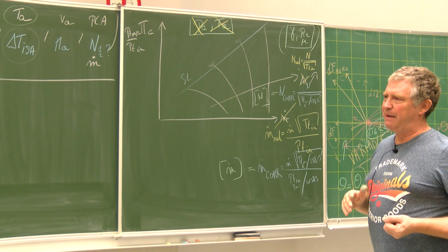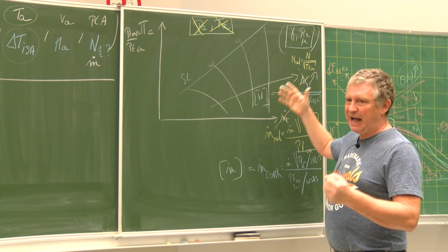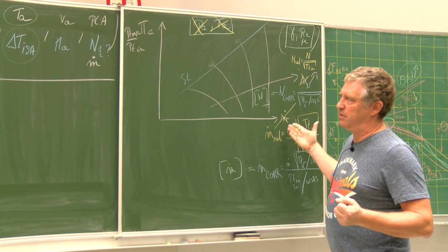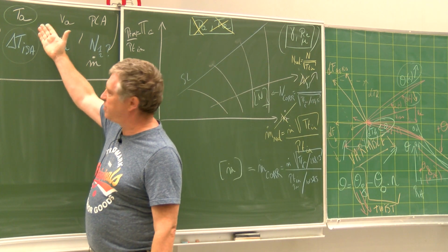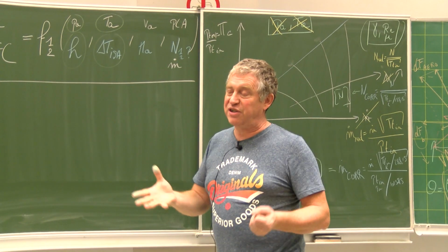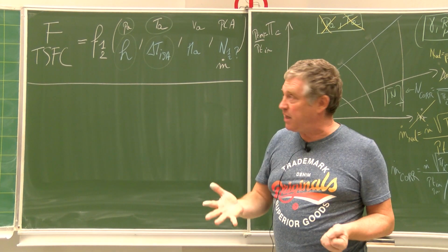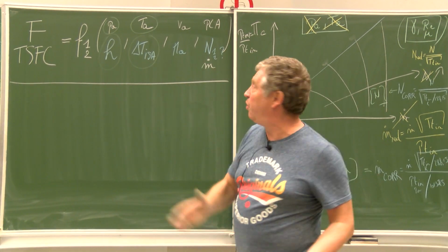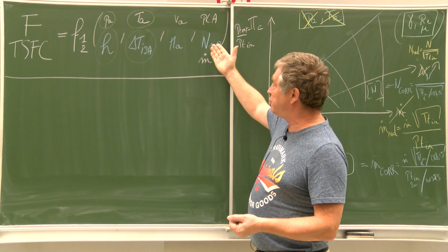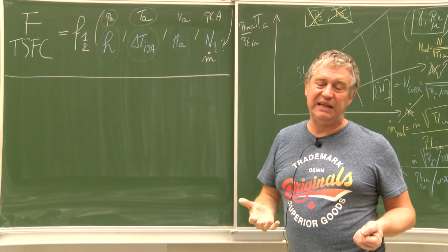And these reduced variables, it's a bit strange, but they have units that are the same unit as what we call the physical variables. These variables are called physical variables because PA, you can measure that with a physical instrument. TA, you can measure that with a physical instrument. VA also, and PLA also. And also the rotational speed, and also the Mach number, and also the altitude, and also the delta T compared to ISA.